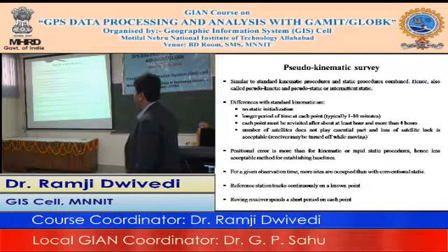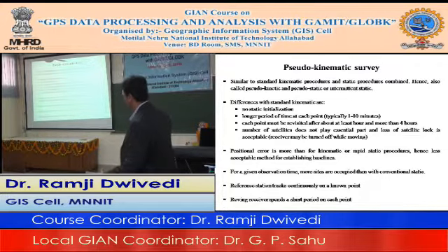The number of satellites does not play an essential part. Loss of satellite lock is acceptable. We are actually occupying the second point again in the future. So positional error is more than for kinematic or rapid static, hence it is a less acceptable method for establishing baselines. Obviously, we cannot do this kind of work for crustal deformation.